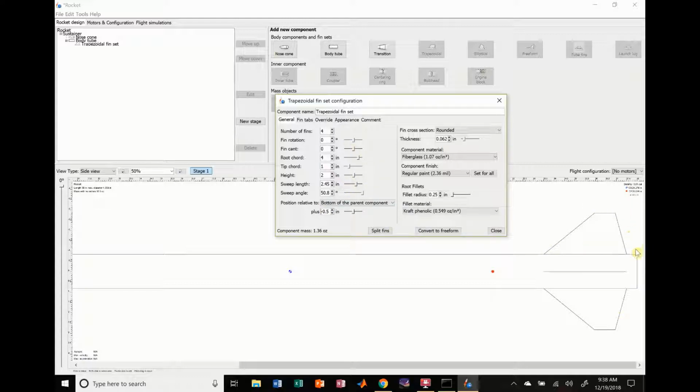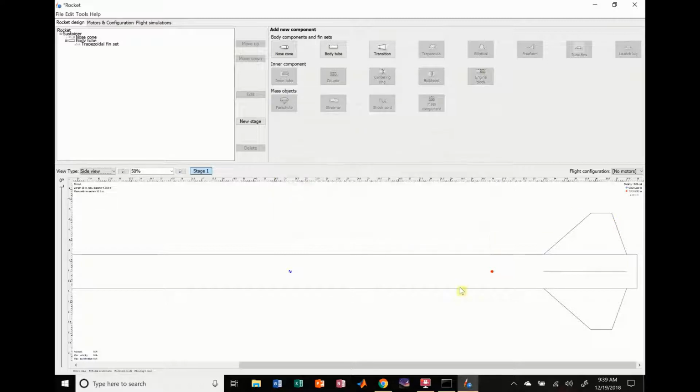So everything's changed on here. These fins look pretty good. And another thing we typically do is we try to shift the sweep angle in the back forward instead of having it basically vertical or coming back off the edge like this. Because again, those fins might impact first, but if you shift your fins forward or sweep them forward like this, they might not strike the ground first. It might hit this bottom portion of the rocket first before impacting one of these fins. So you don't really want to lose one of your fins because it's a big pain to deal with. So we have those fins attached there.